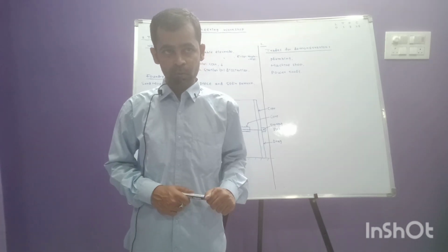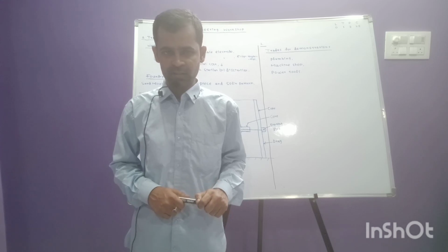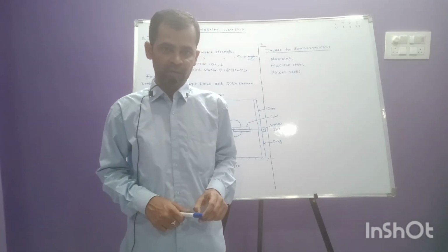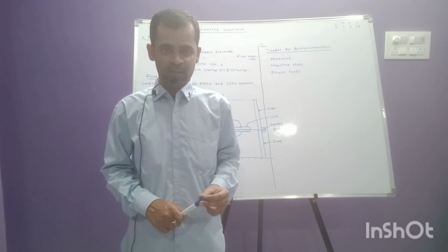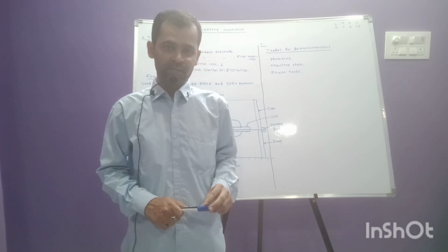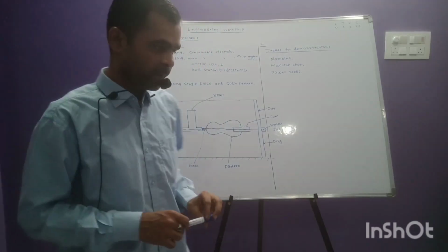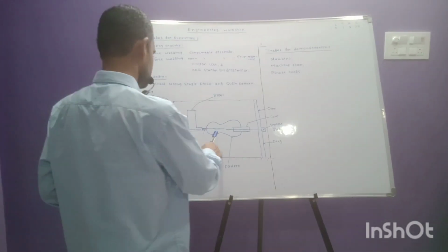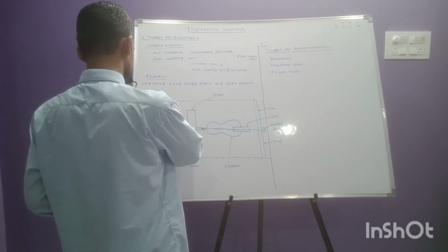Multiple pieces are also used as patterns. A pattern is defined as the replica of the object which is to be cast. The pattern materials may be wood, wax and other materials. The pattern is placed here in the mould, with the pouring basin.